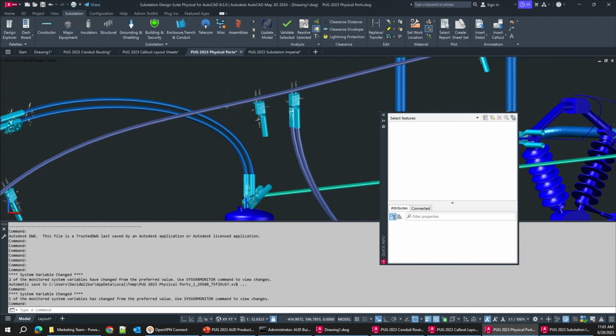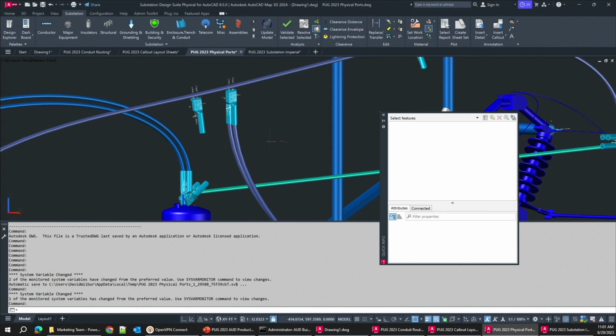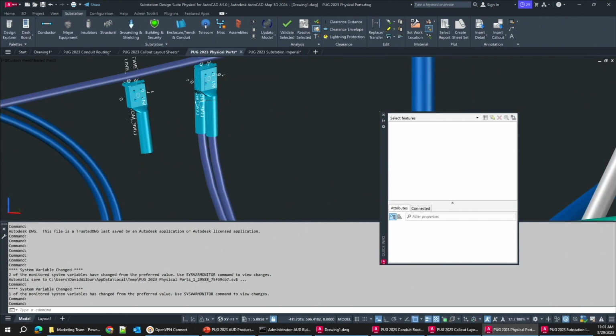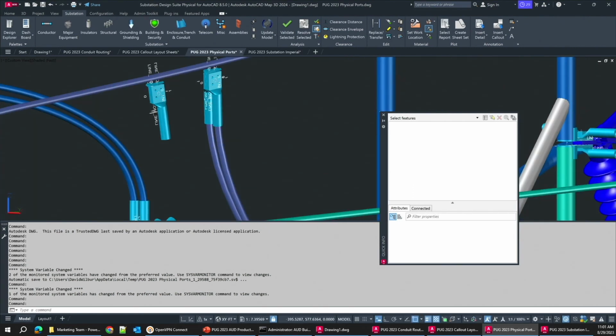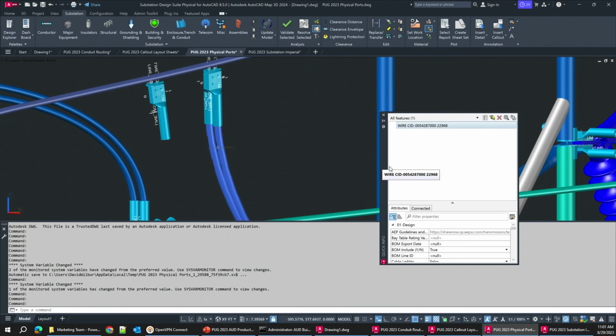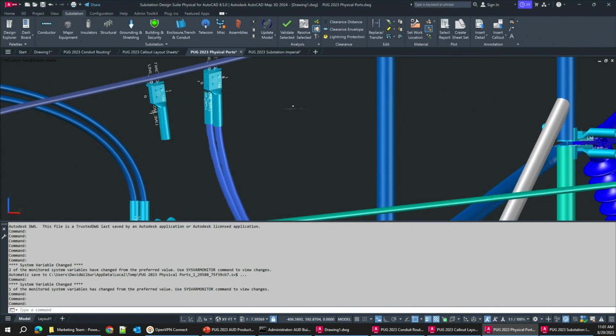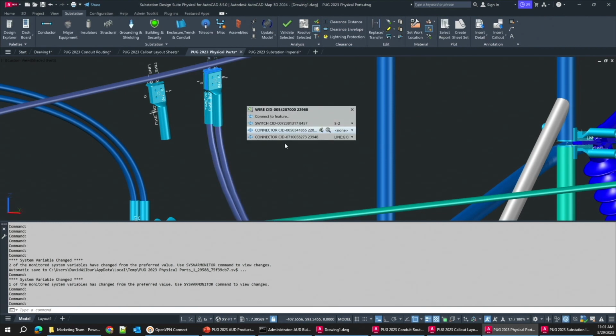So this is a test example drawing for some detailed connectivity. Here you can see I've got a multi-run 3D cable. Over here on the connection tab, you can see what this connection tab looks like, but I'm going to close this and pull up the connections window. This is a little bit easier to use if you're needing to work through fixing connectivity or checking connectivity. And you'll see here that there's also this physical connection button, right?